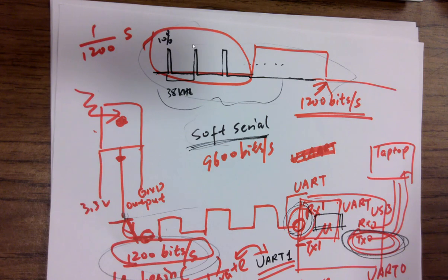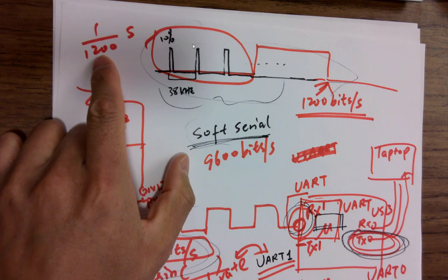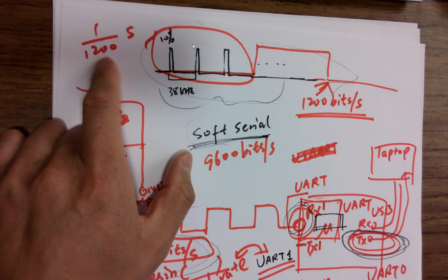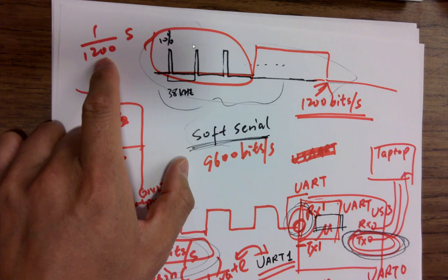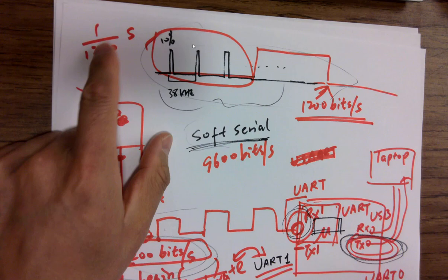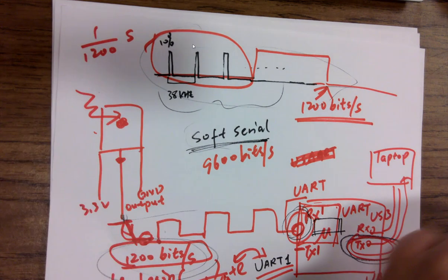And you know the counting frequency, which is 16 mega. It's not difficult to find the number of counts. Any question on this? Here's the time, and it's 16 mega counts per second. So how many counts do you need to make this time duration happen?